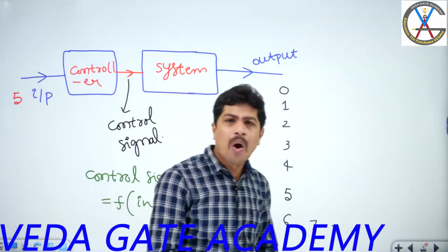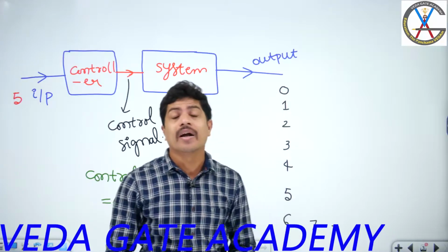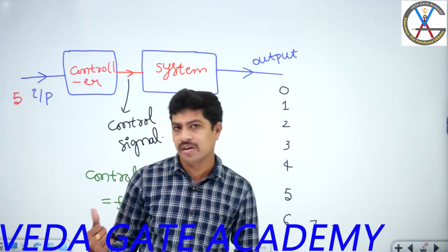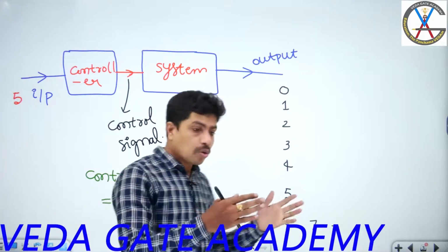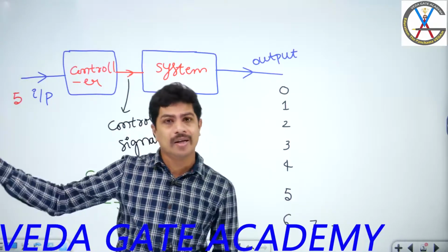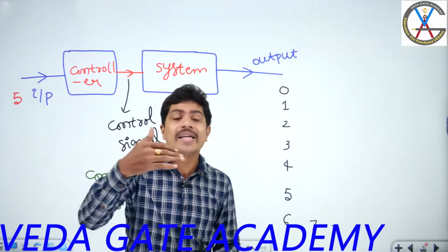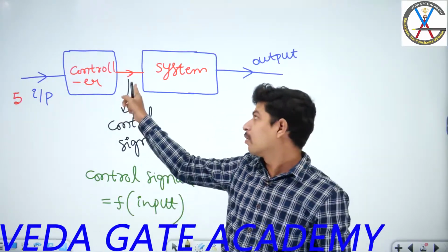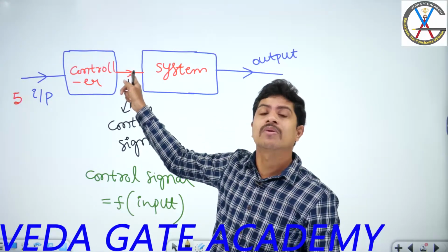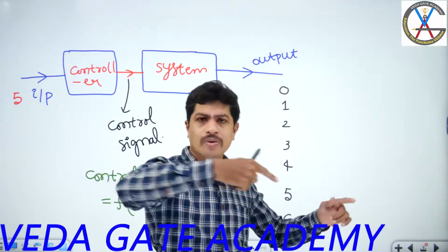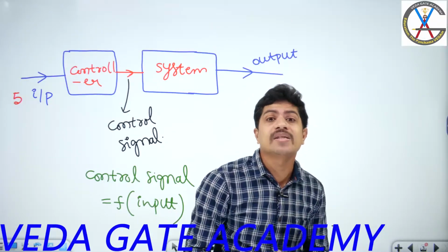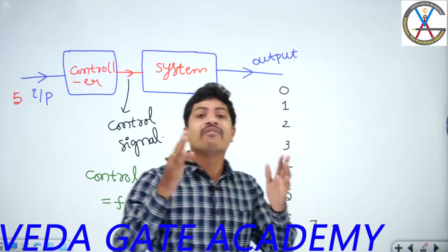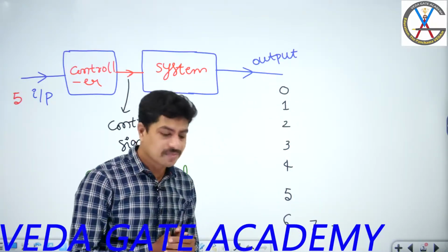No. What is missing in this is, see, to which floor it has to go, we gave the input, but whether it has reached that floor or not, if reached, the output of the controller should be 0 and the input to the system must be 0, then it is going to stop. Yes, what is missing here? Feedback is missing. Feedback is missing. What is feedback?